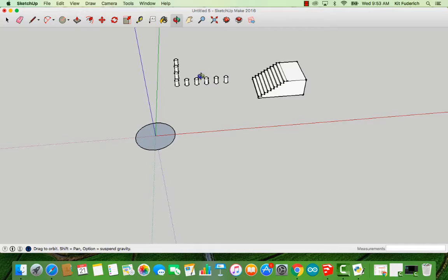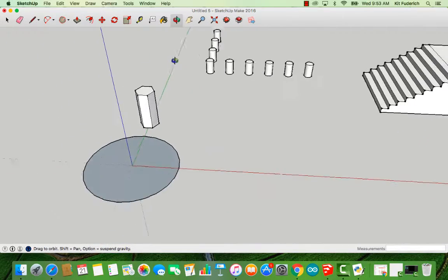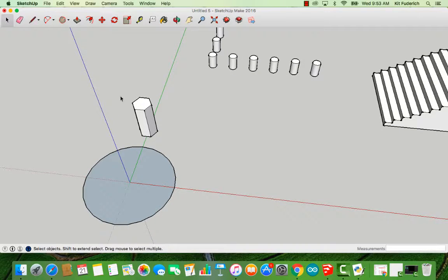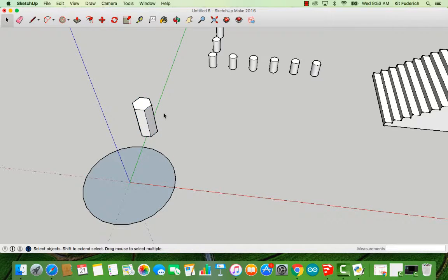What I'm then going to do is create my first Stonehenge pillar, and I'm going to do that outside of the path I just laid down. I'm going to actually do it with the polygon tool this time, because those pillars are probably a little bit angular, not perfectly circular. So there you go, there's my first pillar. What I'm then going to do to make this process slightly easier, so that when I click on any face, everything else will get selected, is highlight my pillar, right click on it, and make it a group. Notice how now when I click on it, everything is selected.